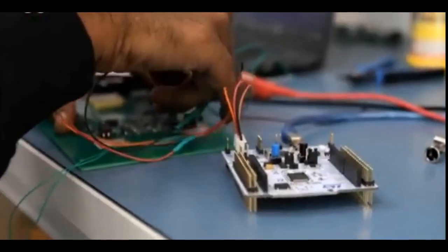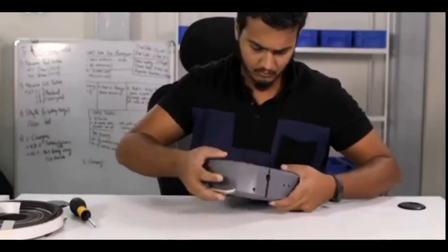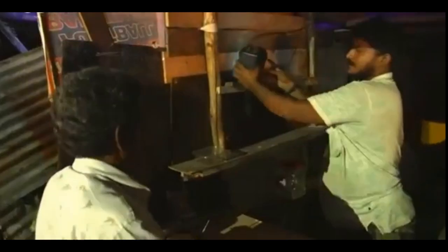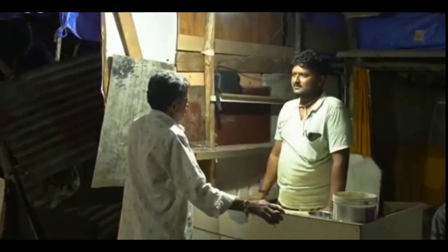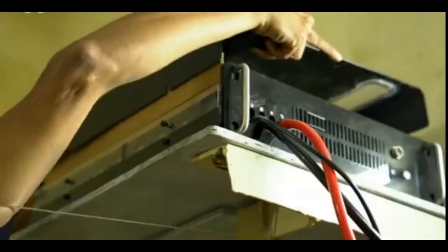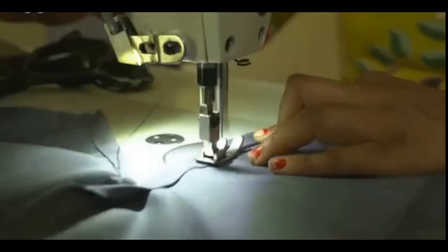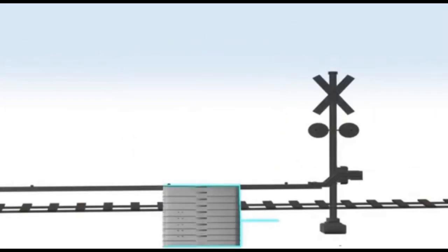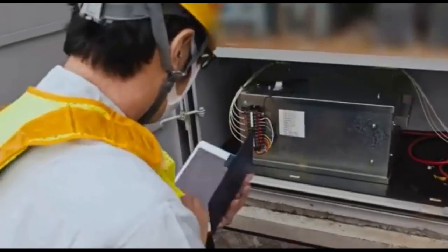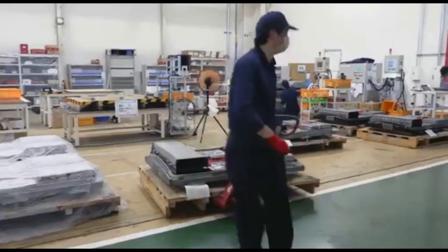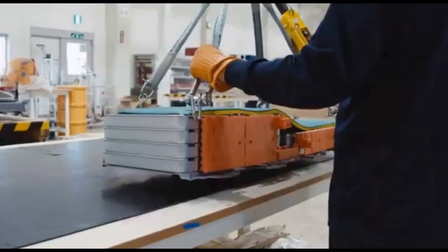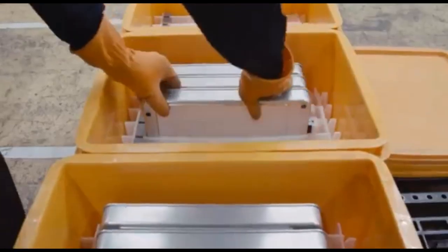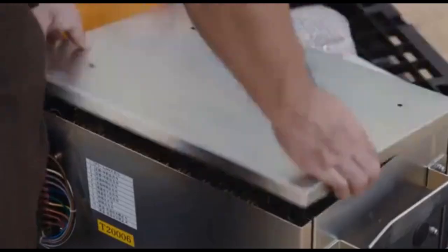Battery management systems software in EVs already collects data on battery parameters, such as voltage, temperature, charging cycles, and state of charge. This data can be used to assess battery health and predict its remaining lifespan. Governments and EV makers must make it mandatory that batteries and their use data are stored to be used later until the battery is finally recycled. We can use data from battery tracking to improve battery management strategies and extend its lifespan to the fullest possible. We can quickly determine which battery is suitable for repurposing or recycling based on their remaining capacity and condition.